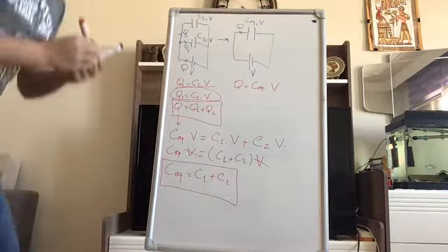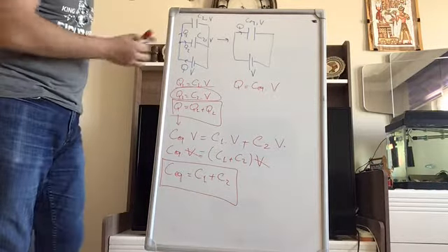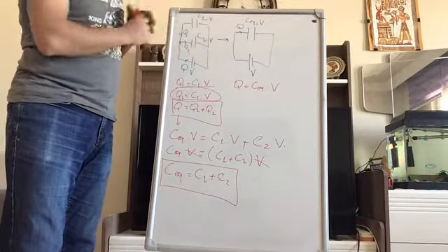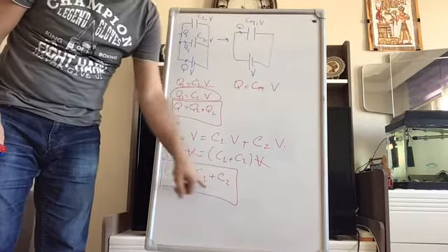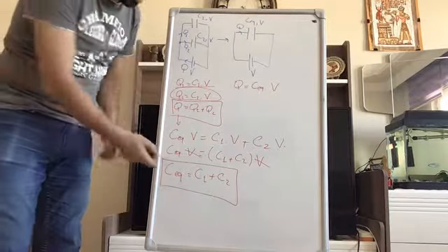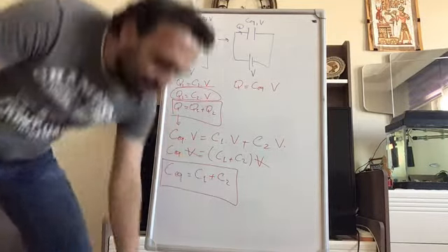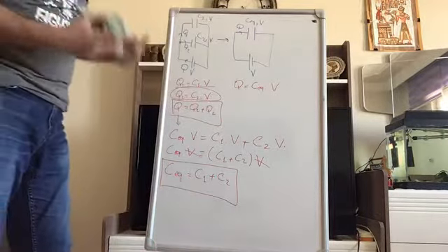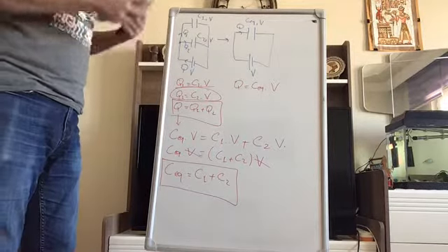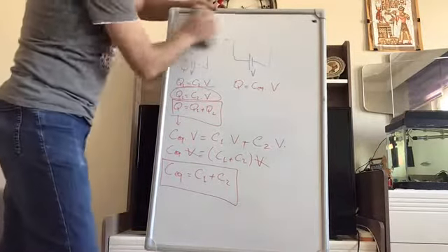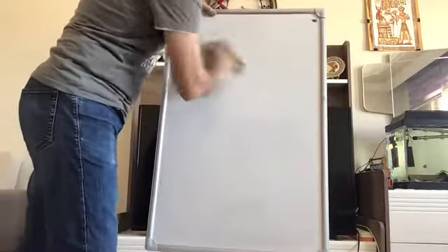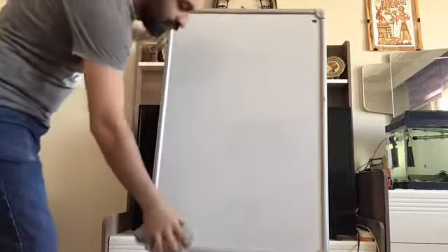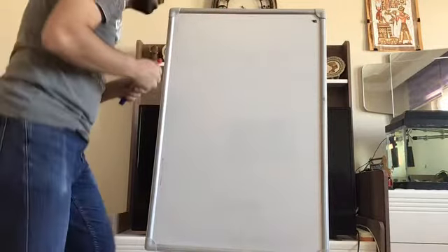So in the case of parallel connections, if you connect two capacitors parallel to each other, the equivalent capacitor will be simply the summation of the capacitances of the capacitors. So C equivalent will be equal C1 plus C2, and it is easy to generalize it. What happens if we have three or more capacitors in the parallel connection? Let us finalize this discussion with the generalization of this C equivalent relation.